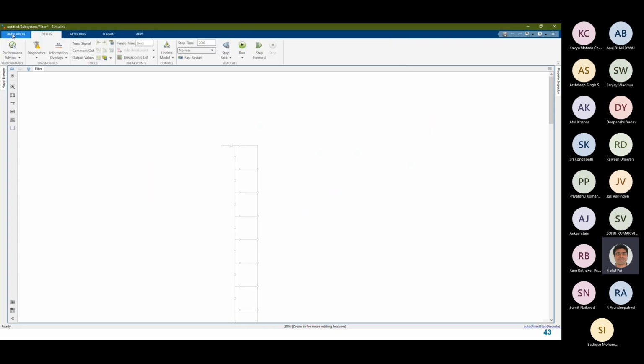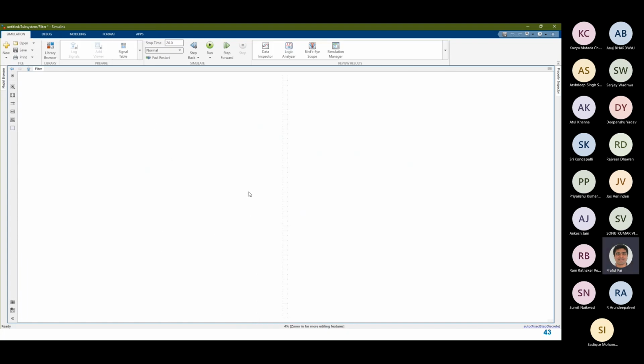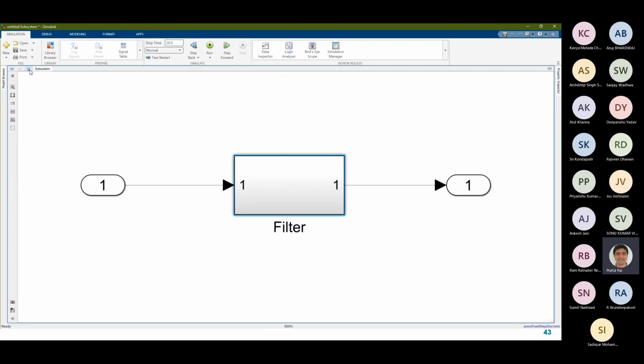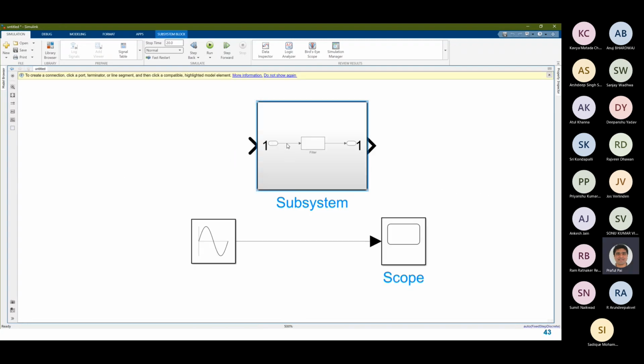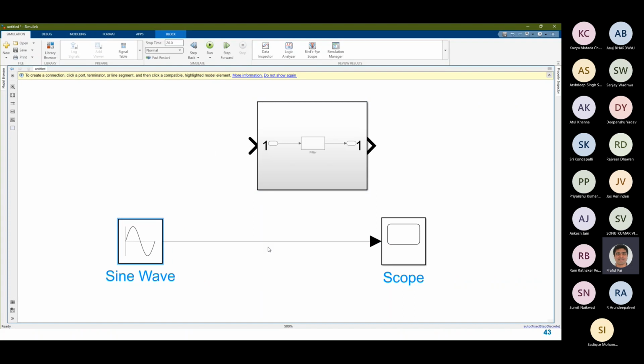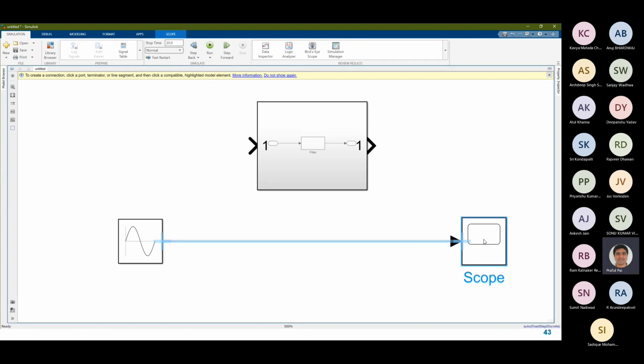So the idea is, again, how do we work with this? If you are designing a system which you want to implement on an FPGA, you design your golden reference in MATLAB. You design how the ideal system should behave, and then go ahead and do your fixed point design, because your golden reference will often be in floating point, right?